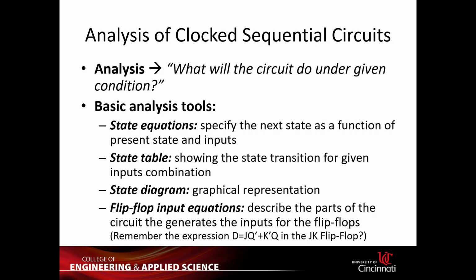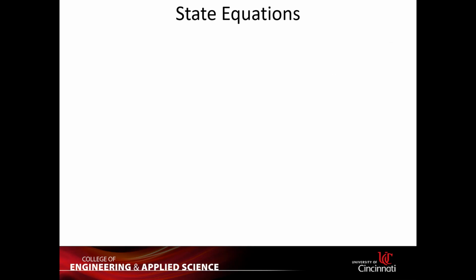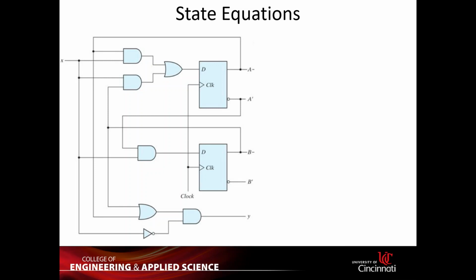A state machine is basically another term for your sequential circuit, because a sequential circuit transitions between one state and another. Those tools are your state equation, your state table, your state diagram, and the flip-flop input equations. First of all, we will go through the state equations.